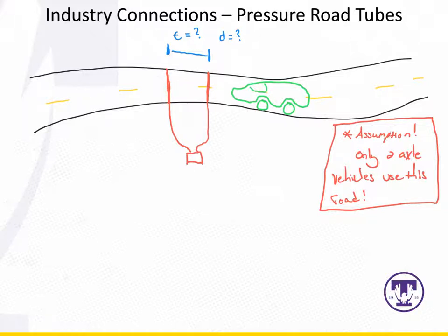So we've talked about the distance of separation between tube 1 and tube 2 and how that affects the speed calculation and where you get that distance. We've talked about the time it takes to go from tube 1 to tube 2. And we've talked about that we're only going to handle two-axle vehicles. And we've talked about that this should count how many total vehicles have run over the tubes. We need a reset button on the HMI to be able to reset the total cars counted and the average speed for a vehicle traveling down this road. So we need a reset button.